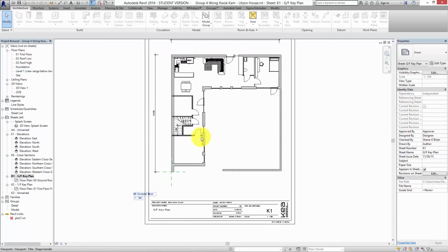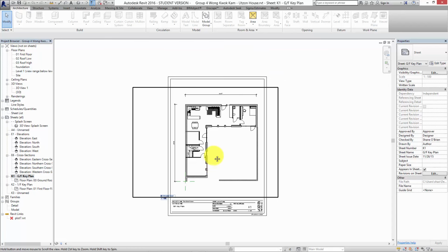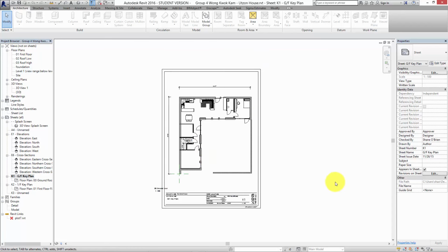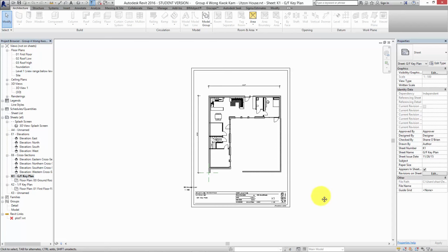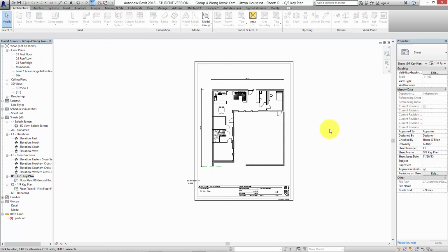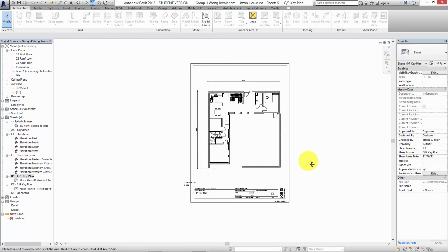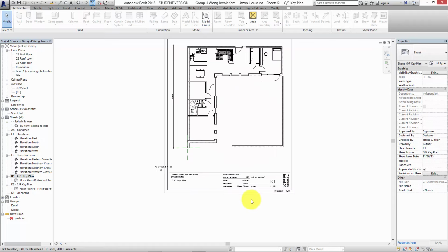So, for example, when you insert the first of all, maybe an A4 size sheet is not the best sheet to use. I would say an A3 is more likely because an A4 is usually just too small. The only time you would use an A4 sheet is if you make a key junction detail or something. In the old days, we used to use A4s. We used to fax them to site. I don't even know if they use faxes anymore in building sites. They probably have all kinds of stuff going on. But an A3 is the most likely one to use.